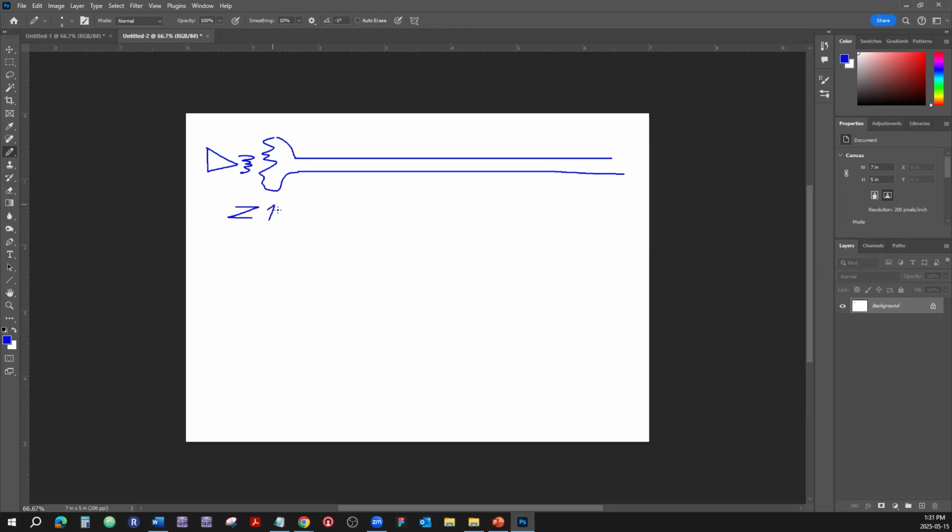It's a step-up transformer. It steps up the impedance. So here we're going to have something like 8 ohms out of the amplifier. I'm going to step up the impedance to not 8 ohms, but maybe 1900 ohms, 2000 ohms, 1500 ohms, 1200 ohms, something in the range of that. So the impedance is going to be low on this side and high on the other side. Now we have something we can work with.